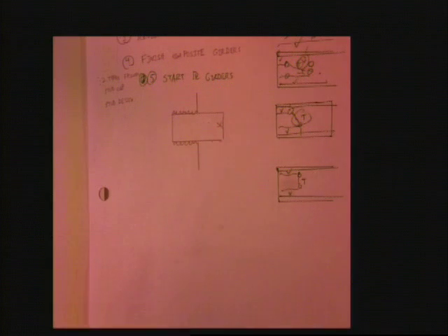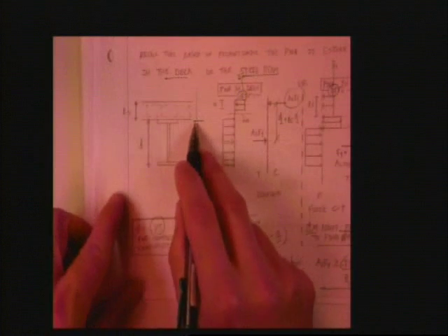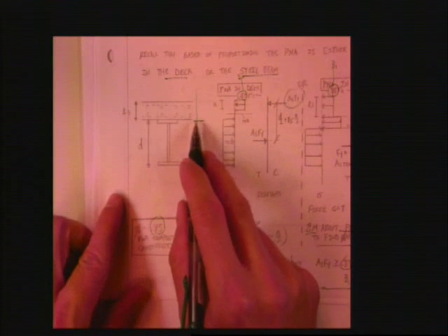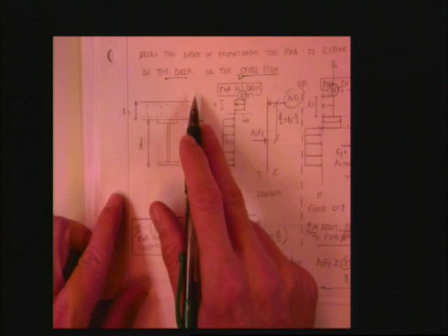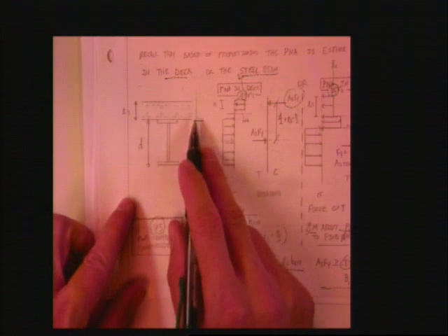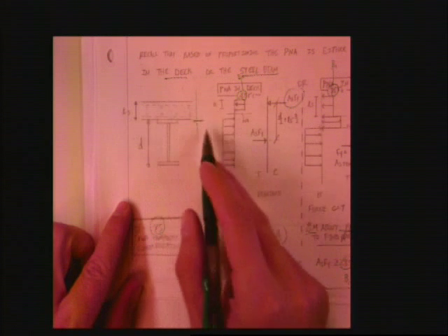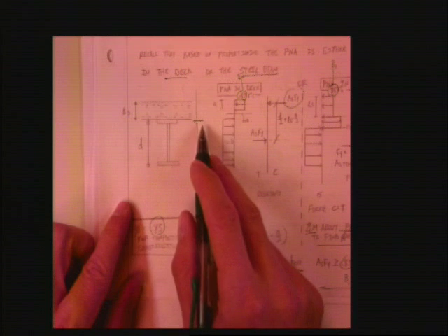Sum the moments. That's exactly right. Really, you find this. You assume the neutral axis is right here at the interface between them. You sum the moments below. You sum the moments above. Okay. And what do you compare? What are you looking for? Which one's larger, right? It's not really summing the moments. It's summing the forces, the resultant forces.